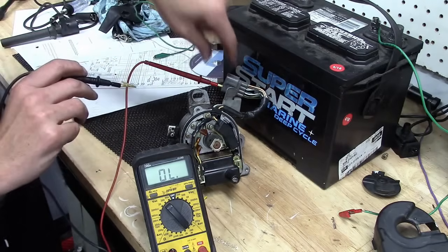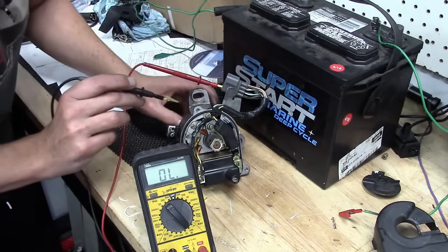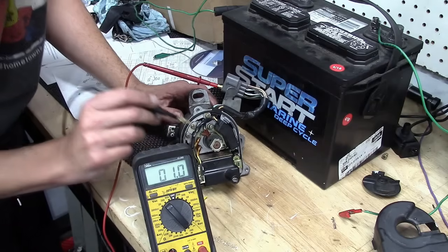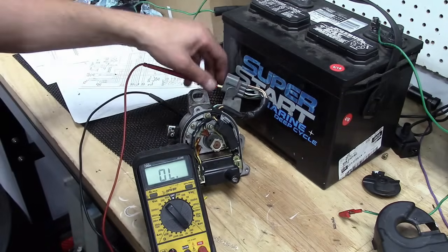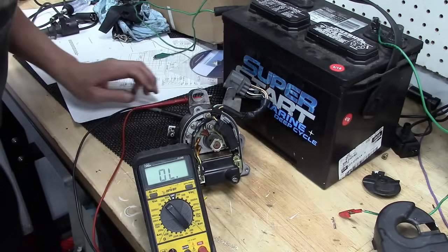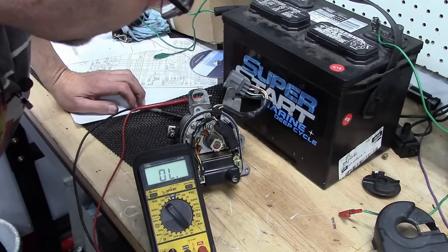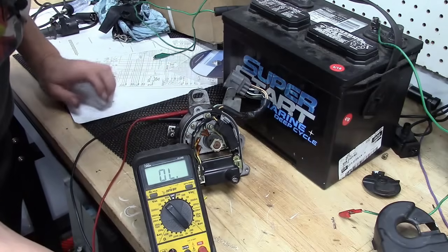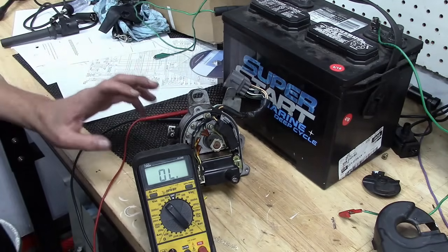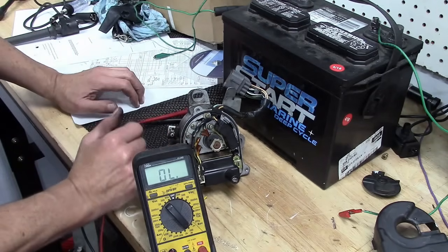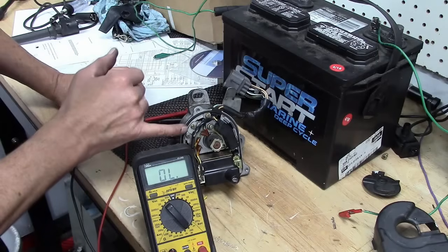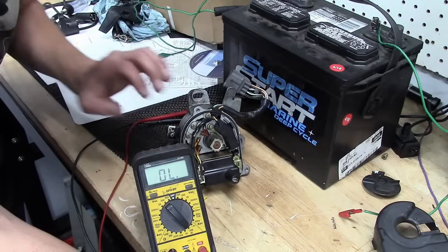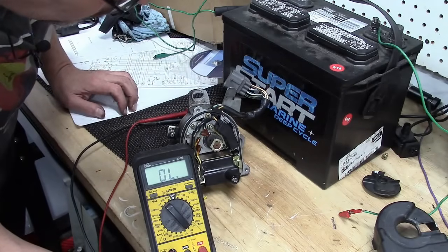We know there is ignition input from the PCM into there. The question is, is it getting to the ICM? And it is. It does get to the ICM. We know that. We have continuity there. One thing that is occurring to me, how to test this ICM. We would actually probably need it on the car to test the ICM, but it doesn't matter. If we find this coil is good, this ICM is bad. Period. End of story. So it doesn't matter. We don't really need to test the ICM. We can just test the coil.